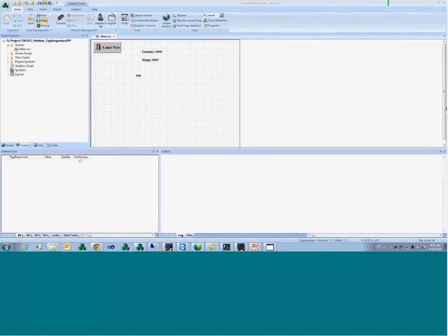So I got a question about why we are having communication errors sometimes detected on the output window. Well, we send a message for the ADS. In my case here, I have a very busy network because this is not a device network. This is my corporate network that I'm talking to. All the TwinCATs, the ADS is trying to talk as fast as possible, but we are also exchanging mails. We are also downloading and uploading things. Today is a very busy day here in the company. So we are in the same network for everything. So the network is actually causing the errors in my case here.